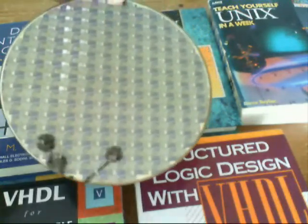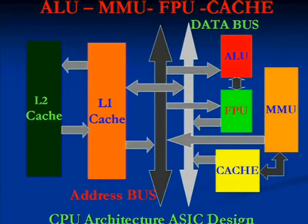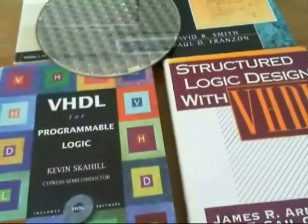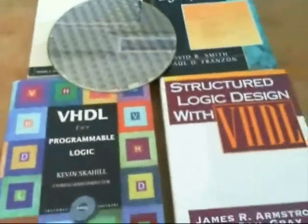When all elements are placed, global and detailed routing is run to connect all the elements together. Also, after this phase, a complete simulation was done to ensure the layout phase was properly completed.